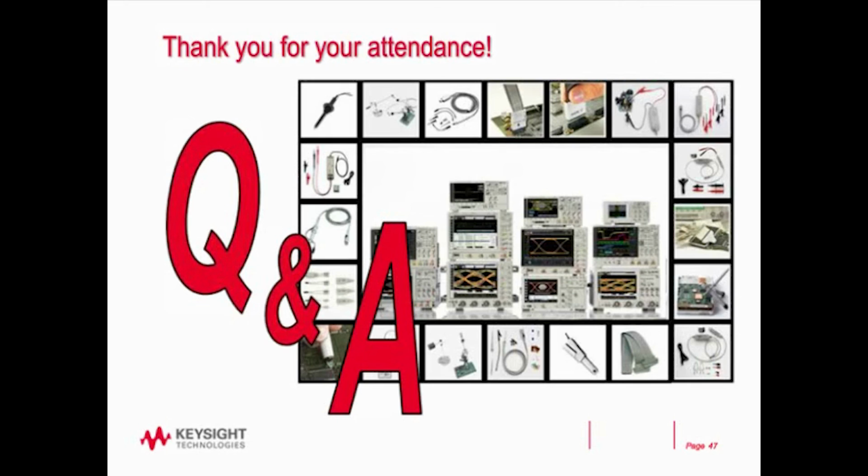The power rail probe, the advantage, if we were to use it for the power supply rejection ratio, is that you could use it driving into 50 ohms, which on the scope typically has a lower noise floor, and so it's going to give you more accuracy. And then also a couple of our scopes, like the 6000 series, has even a lower noise floor into the 50 ohms. So it might make those low-level output measurements better. But today it is not compatible.